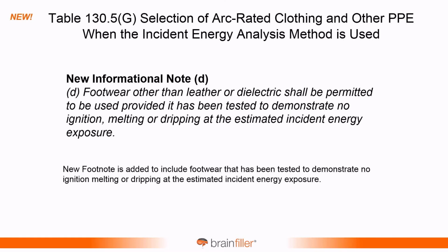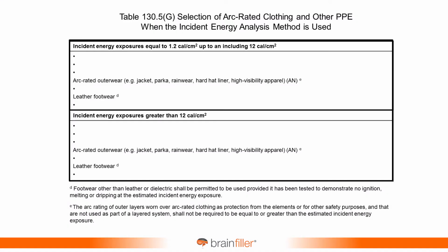Another is about footwear. In the past, it's been permissible to wear leather footwear or dielectric footwear, and that was really all that was mentioned. And now there's an informational note that states footwear other than leather or dielectric shall be permitted. So you can use footwear other than these two types. Permitted to be used, provided, oh, there's a catch. It's been tested to demonstrate no ignition, melting, or dripping at the estimated incident energy exposure. And so that's a new informational note also added to the table for selecting arc-rated clothing and PPE, and also for the PPE category table.